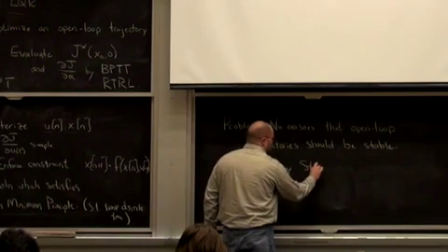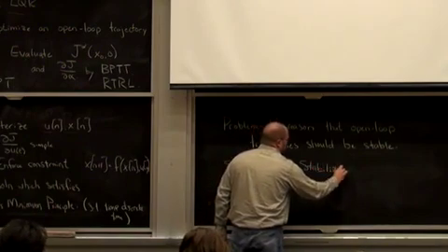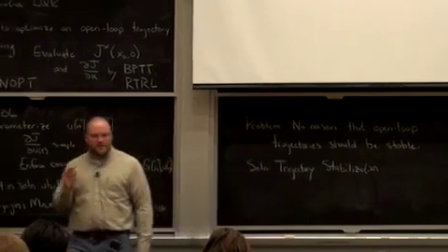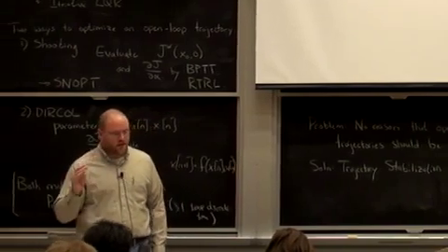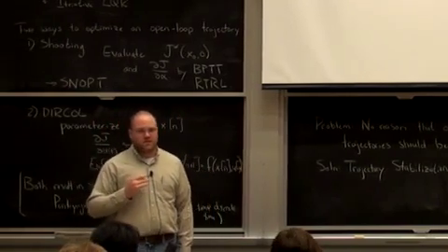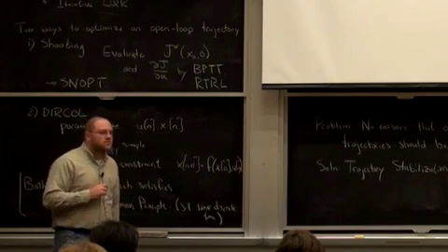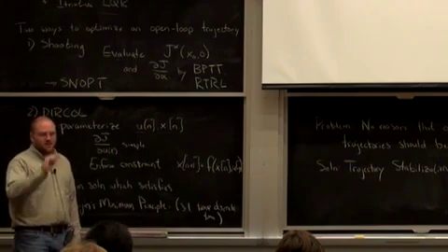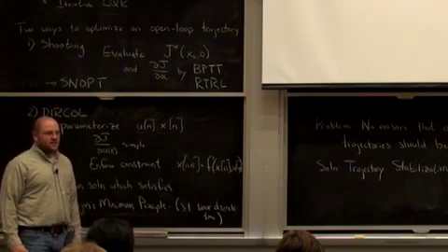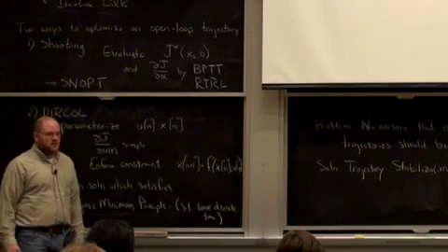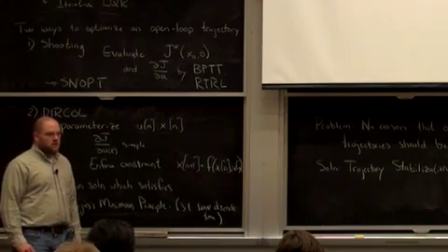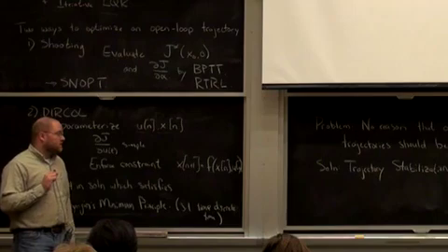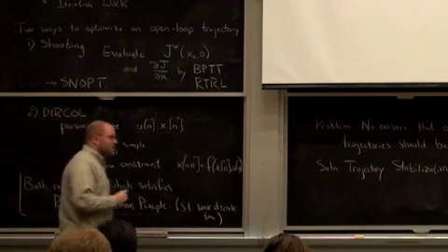Now, for those of you that have been playing with robots for many years, when you hear trajectory stabilization, what do you think of? What kind of tricks do people use for trajectory stabilization? Sliding surfaces, that's a good one. Slotine often will design a sliding surface and squish the dynamics, right? I guess that's actually pretty encompassing. A lot of the trajectory stabilizers are based on sliding modes or feedback linearization